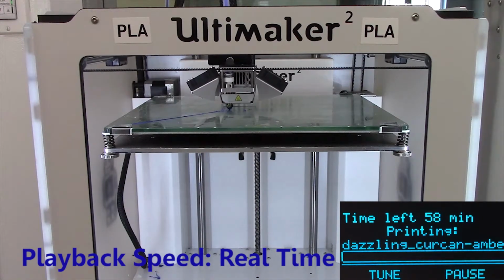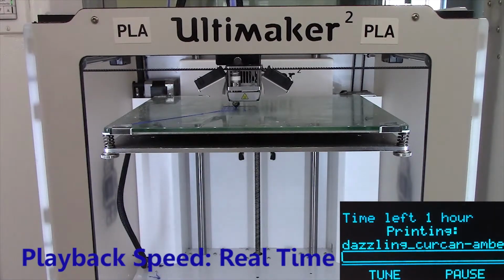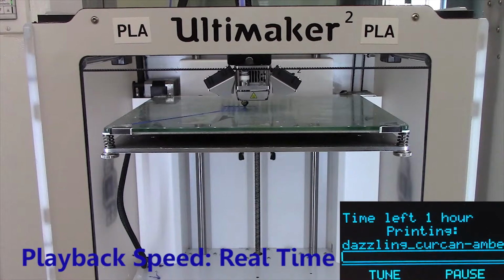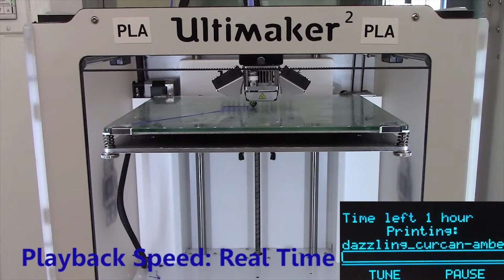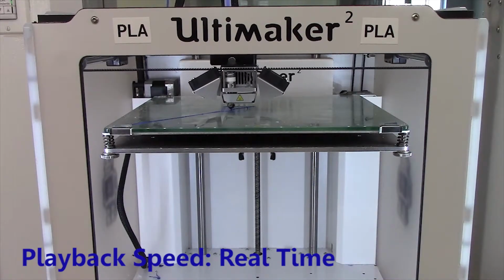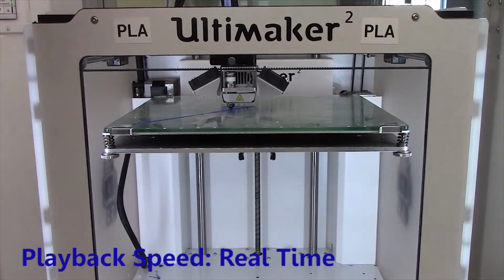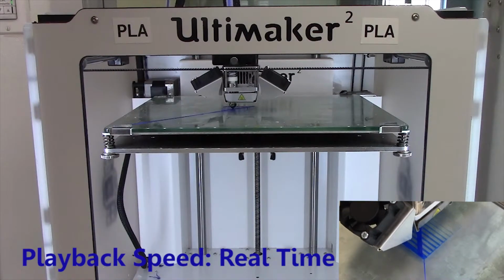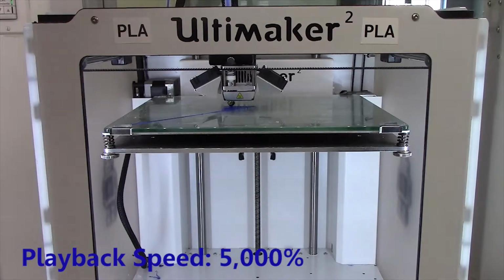And as the print begins, the first component that is being laid out here is the raft, which, if you recall, is the interface that we selected between our part and the printer tray. As I mentioned before, most prints fail during the initial stages, so I recommend watching your part for at least the deposition of the first few layers if you can, to ensure no problems arise. Taking a view from above the machine, we're able to see that the raft is constructed via a lattice pattern with material deposited at a 45-degree angle relative to adjacent layers.